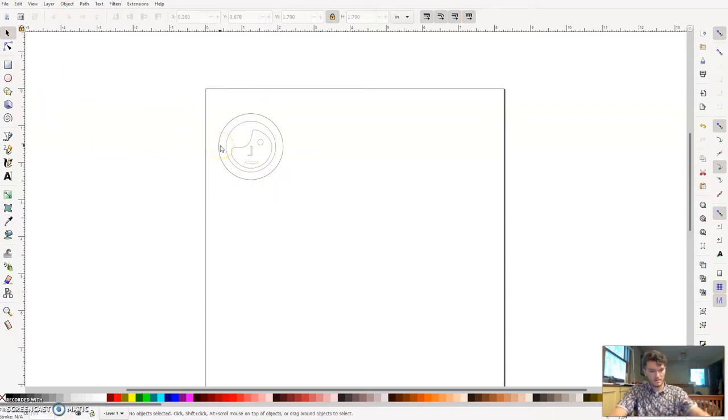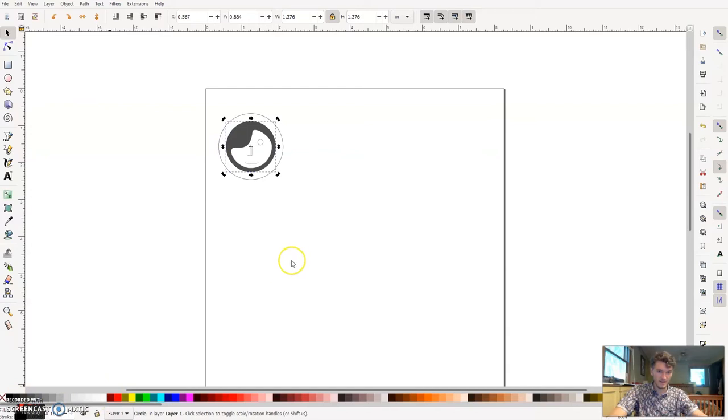Now, as you can see, I've taken all the color out. Obviously, I could come in here and I could give things fill color, and I could do whatever I wanted in here in Inkscape, but I want to make sure that I can see the line. We're going to cut this on the laser in vector mode, which means that the laser tool head is going to follow all of the lines, and it's not going to care about colors. It's not a color printer.